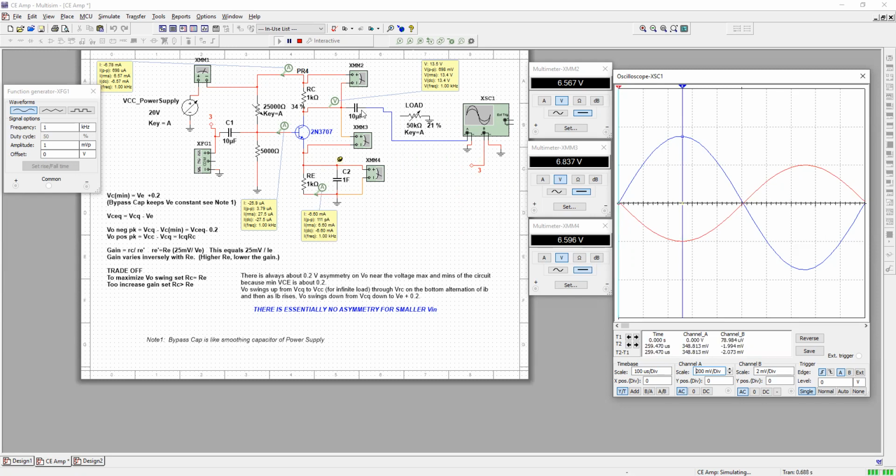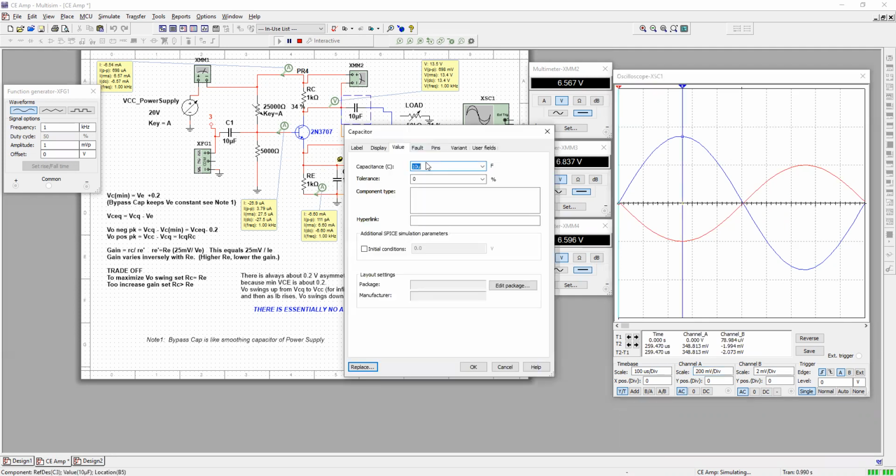Let's think about what we would expect. So bigger capacitor acts more like a wire, passes along all kinds of frequencies, low and high. Smaller capacitor will choke the voltage at the load. Okay, and it will store the voltage of lower frequencies longer. Well, 10 microfarads is what we have here. Let's check it out. Let's see what happens when we go very low. Let's do 1 nanofarad.